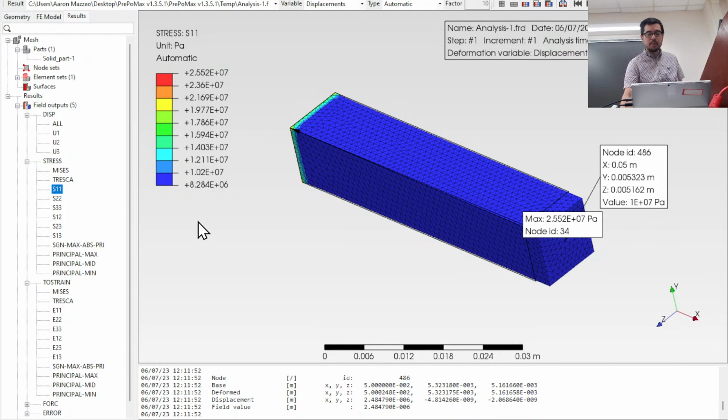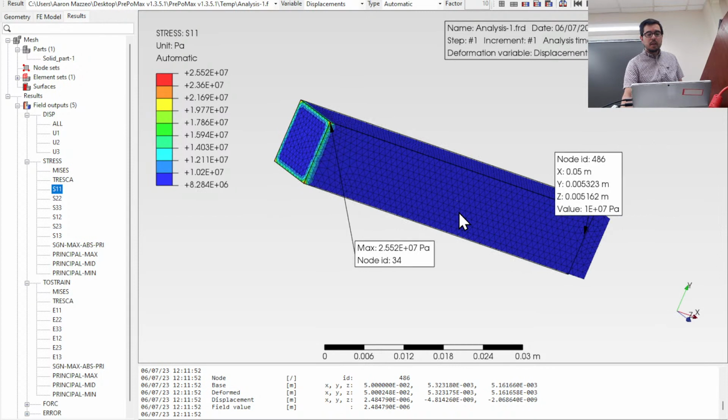Why is there such a big range of the stress? That's because of what we call edge effects. Remember, this is constrained on this side in all 3 directions. So you have Poisson ratio telling us that it's got to shrink a little bit in those directions. It's going to be like, I really want to shrink, but I'm not allowed to shrink. So the stress gets to be very high at this face where there are end effects.